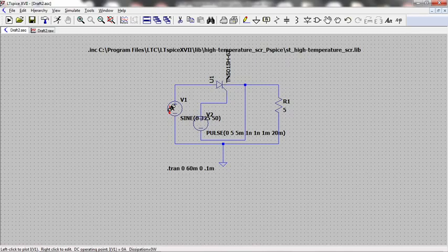See, this is power. Once the SCR is turned on, it is acting like a closed switch. It is just like a conductor. So at a firing angle of 90 degrees it turns on, and till 180 degrees it conducts. So during that time the load is connected to the source. So the load will receive the entire voltage from the source from 5 milliseconds to 10 milliseconds. That's all.